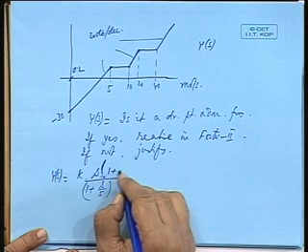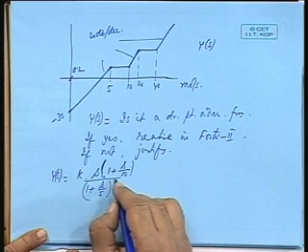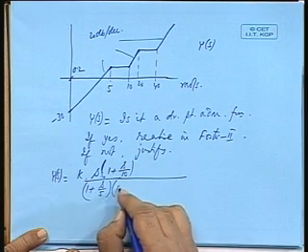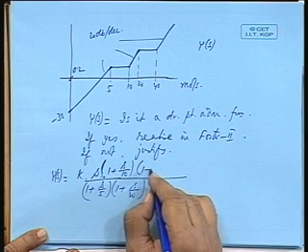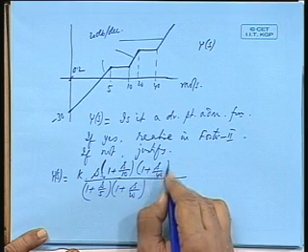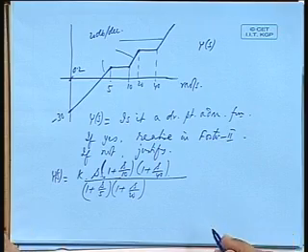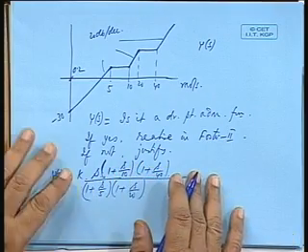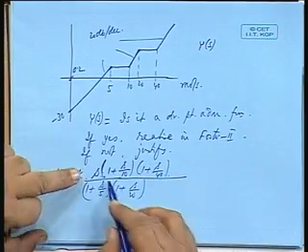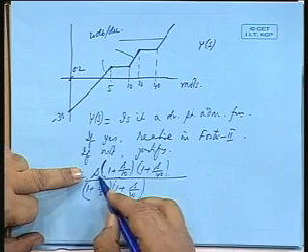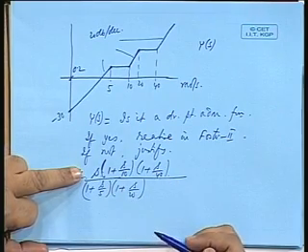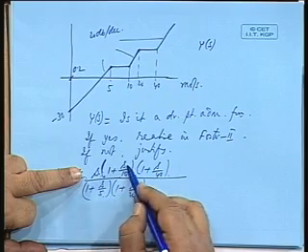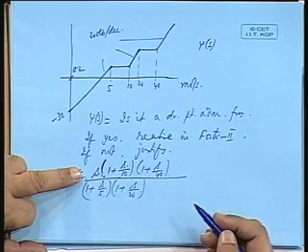Numerator again it will be 1 by S plus 10, 1 plus S by 20, 1 plus S by 40. Okay. Before we go into the evaluation of k, let us see k is just a scaling factor. Is this an admittance function, driving point admittance function? Yes, because zeros and poles are coming alternately.